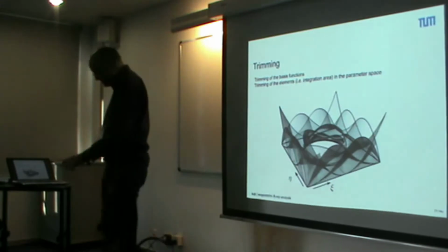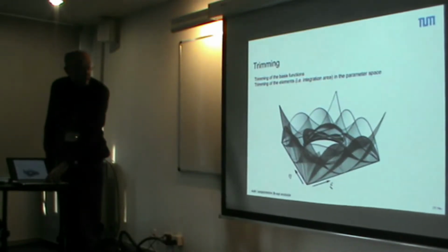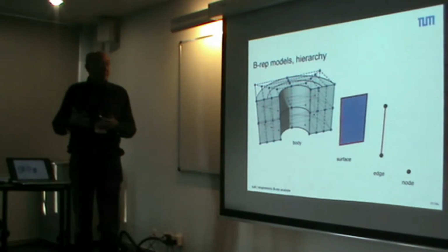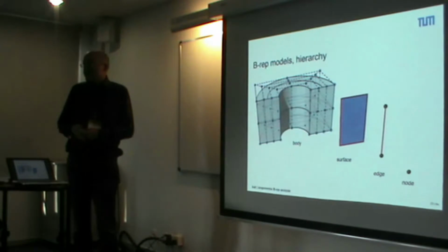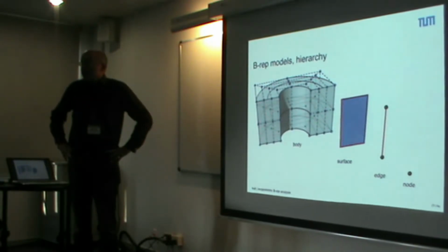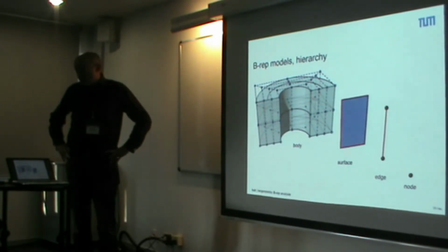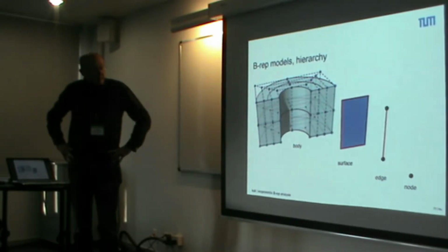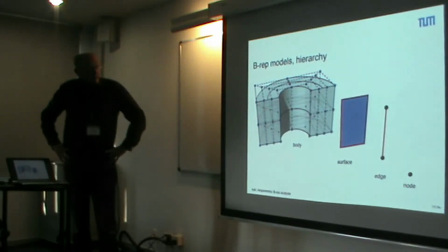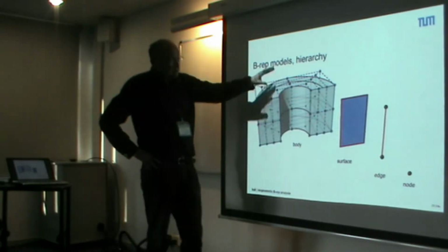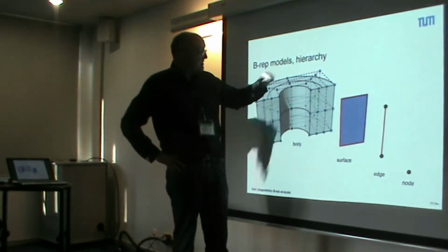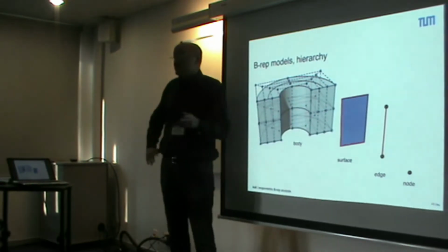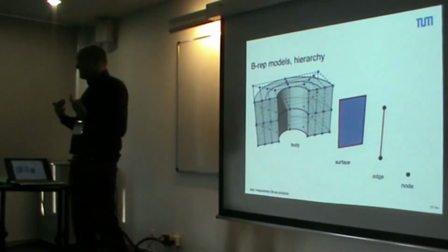You may treat them with this fictitious domain or not, but anyway, we have to come up with that. On top of that, we deal with BREP models typically, and it is quite interesting that we can make use of this information, which just drops out of everyday's available CAD environments: the overall body is typically composed in a hierarchical manner from nodes to edges, surfaces, and bodies, and you get everything of that from your CAD environment.